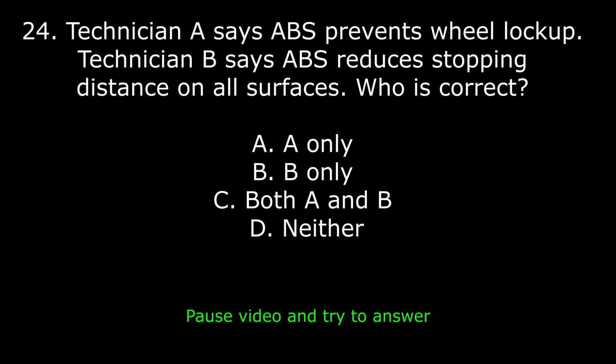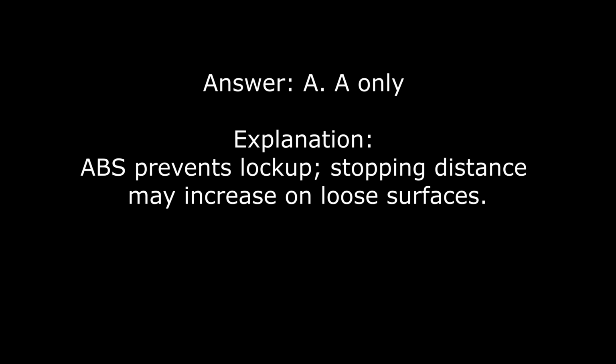24. Technician A says ABS prevents wheel lockup. Technician B says ABS reduces stopping distance on all surfaces. Who is correct? A. A only. B. B only. C. Both A and B. D. Neither. Answer. A. A only. Explanation. ABS prevents lockup. Stopping distance may increase on loose surfaces.